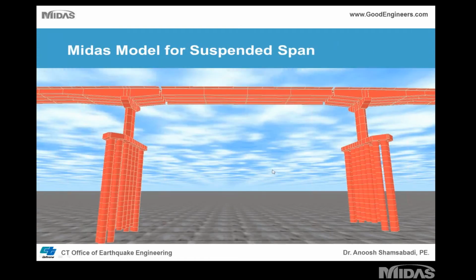Another closer shot of the Midas, looking at even the drop span. That span is about 225 feet in length. It's about 30 feet of cantilever, and about 165 feet is the length of what we call the drop span at the main channel. And this is the main channel, and I have instrumentation at the piles, at the pile tip, top of the pile, and at the superstructure.